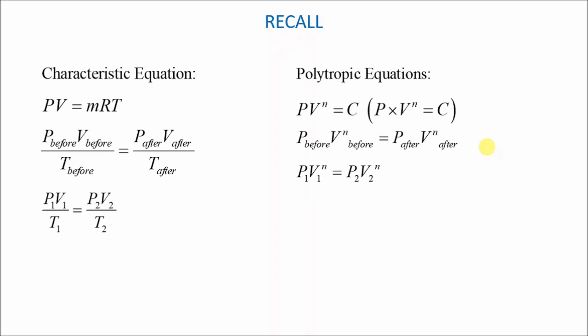Sometimes they may not say that it's polytropic, but they will just say take the polytropic index as being maybe 1.29 or something like that. Immediately when they give that away, you know that this process between 1 and 2 was polytropic, and therefore you can use the polytropic equations. But do not use polytropic equations when you are not told that the process is polytropic.